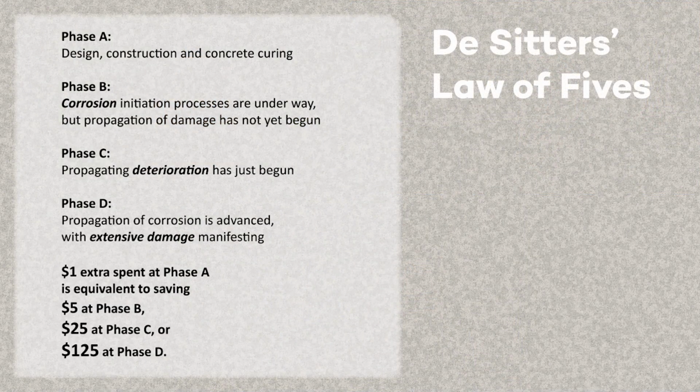Yeah, just sensible strategies. No, I think that's right. It will be a challenge of the industry, though, getting that mindset change. I think the Australian Concrete Repair Association put out, a number of years ago now, that $1 spent in the construction phase saves a multiple of five. Essentially, the long term result of not doing it right is premature deterioration, and you could get to the point where it's not going to last the service life that it was intended. You end up building again before its service life. So you've got to weigh up those sort of models as well when we're talking like this. That's good.